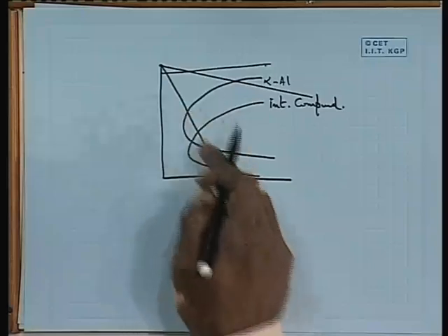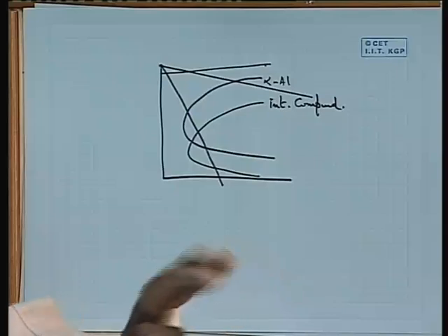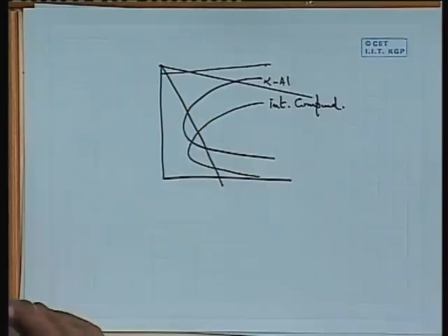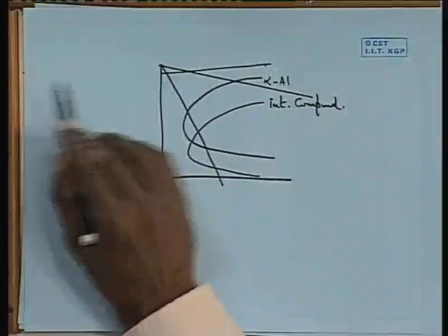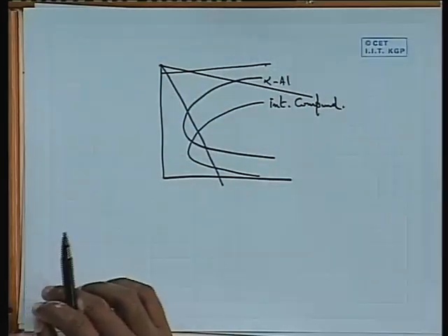you can have a combination of aluminum. So, initially aluminum comes out, and the remaining liquid will come out as some of the intermetallic compound particles, so that you can have these particles distributed in an aluminum matrix. Otherwise, one can also cool it slightly slowly, get a supersaturated solid solution of aluminum and then precipitate it by aging. That also one can do.